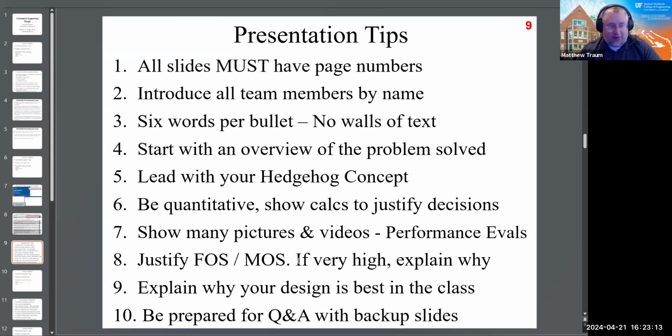One great example is if you are buying parts commercial off the shelf that have all of the features and all the functions that you want, but they're just a little beefier than what you need, but would end up being much less expensive to acquire than making that part yourself. That's a situation where you could end up with a part that has a really high factor of safety, but you pick it anyway because it's the best option to keep the cost down.